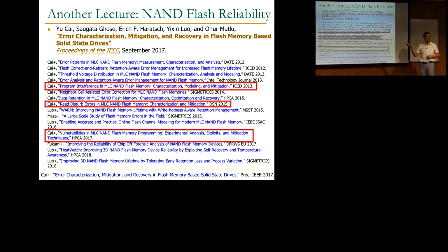And actually, the fine-grained manipulation of the read voltage is what enabled a lot of our studies. Today, if you want to manipulate the read voltage on a flash chip, you have an interface, but that's very coarse grain. You need to really know what those special commands are to be able to get to the voltage distributions.